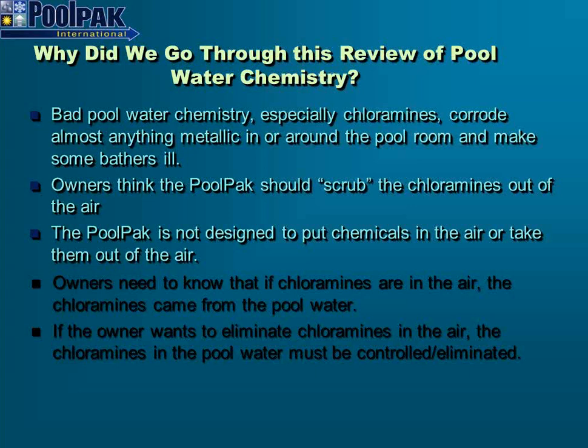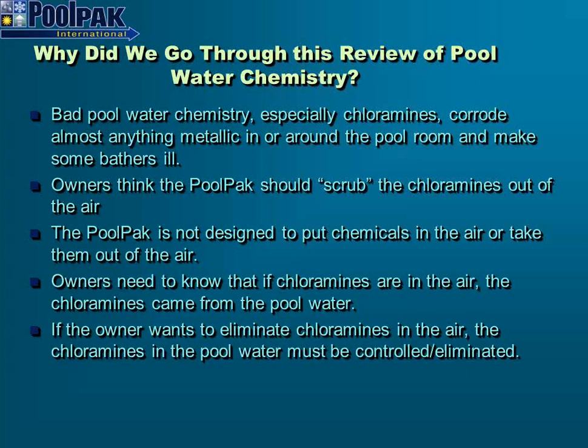So engineers, have a discussion with your clients. Ask them about their pool maintenance procedures. If you can, talk with the pool manager, the person who's actually testing the water, monitoring the water, and treating the water. And again, if we want to eliminate chloramines, the pool water chemistry must be monitored and controlled properly.